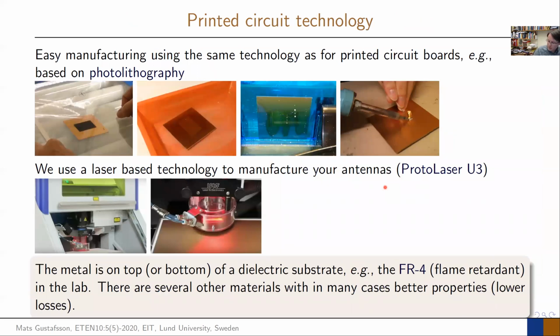And then you can ask how you manufacture these ones. And there are different technologies. The most common one, and especially traditionally most common one, and the one we used in this course until approximately 5 years ago, was something called etching or photolithography that you have up here. So that is a technique that in the lab, you, as the one who's taking the course, actually produce an A4 paper, and on that A4 paper you printed here a rectangle and a little dot.